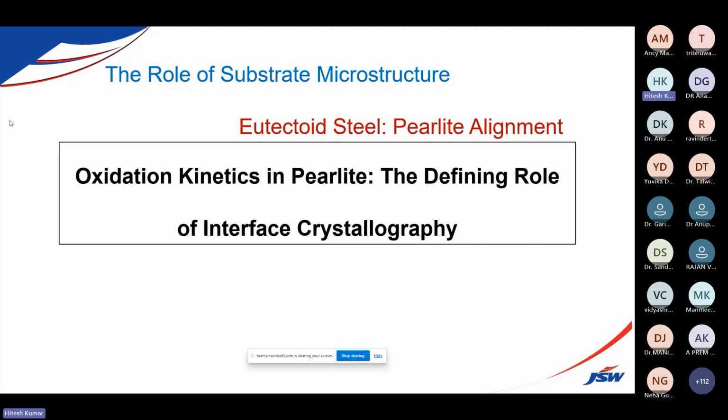To form martensite, either you have interstitial atoms in your material, or you need to deform it at a higher rate. So that is the one we took; the other is a eutectoid steel. Eutectoid is a two-phase material having ferrite and cementite in a lamella structure.